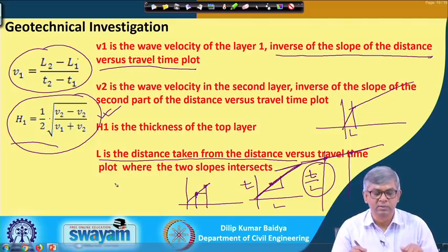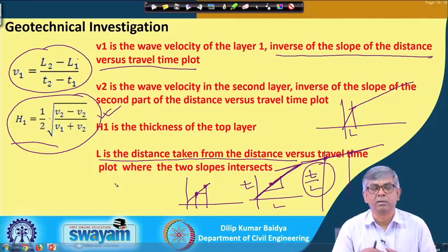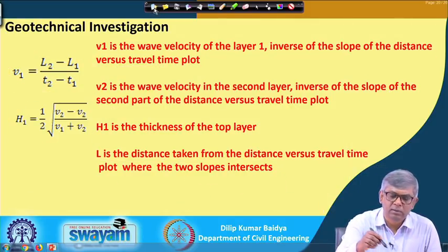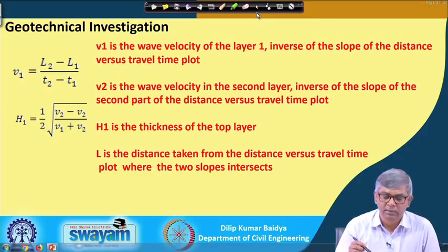So, this is the way we do the calculation by the seismic refraction method. We find out the velocity of the layers, and if you know the velocity of the layer, then you can find out the shear wave velocity. The shear wave velocity is related to this velocity.